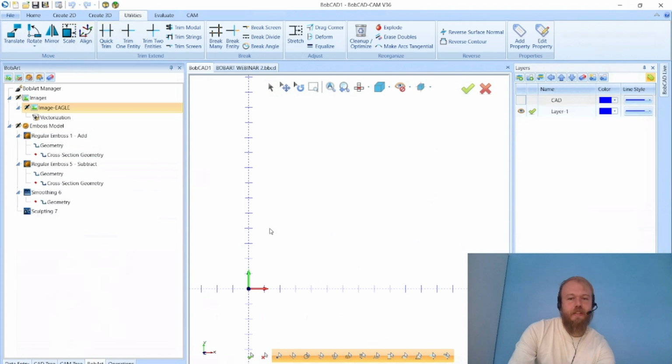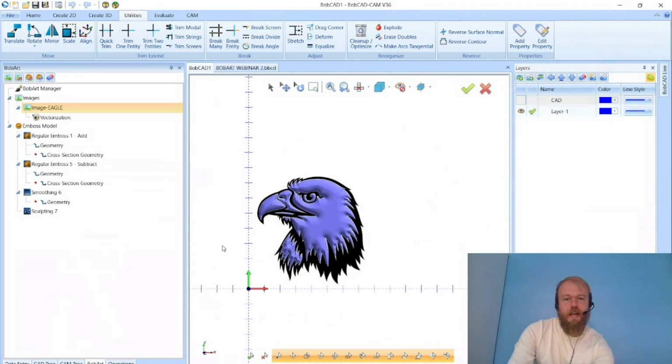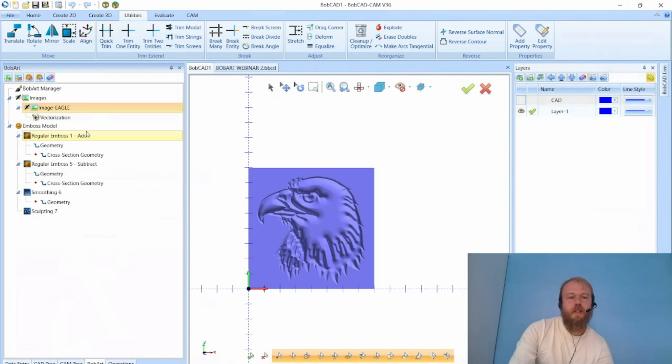So yeah, if you want to test it out, by all means, definitely try that out on your side. You can take a picture. Again, make sure it's got a good background. Put it on a white piece of paper. I'm talking about printer paper, not notebook paper. You don't want any lines or anything like that. You just want a blank white piece of paper you can put your part on. Take a picture of it, straight down on the part so that there's no shadow, and bring it in as an image.